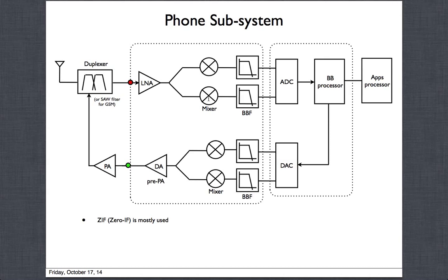For example, let's say your bandwidth was 1 megahertz, and you said every 10 kilohertz away I'm going to put a subcarrier, and I'm going to fill up the 1 megahertz with subcarriers which are say 10 kilohertz apart. Just an example I'm trying to give you. So you could actually have 100 subcarriers, right? In that 1 megahertz range, you could have 100 subcarriers. That way you have information distributed on all of those carriers, so you don't have to worry that all the information is at DC and all the flicker noise or DC offset is really drowning me.